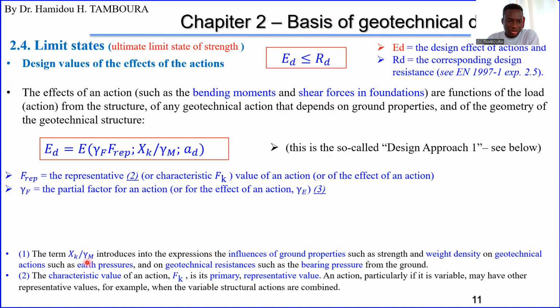So you have two choices. You can use the action itself, or you can use the effect of the action. In case you use the action or force, that one is this one, representative force, representative action. In that case, you have to use this partial factor, kind of safety factor, multiplied by the action, the force.